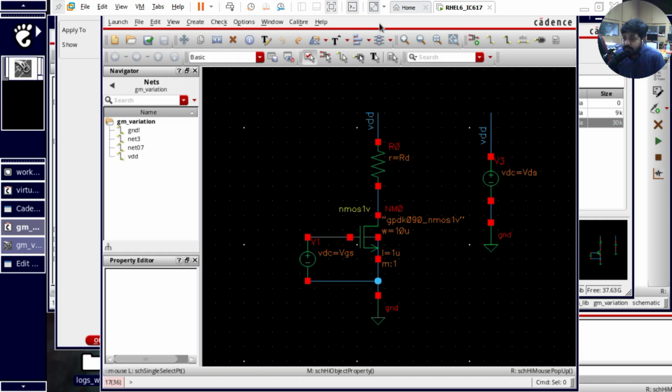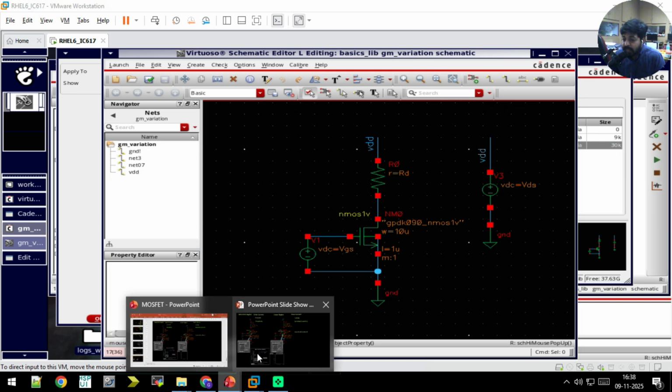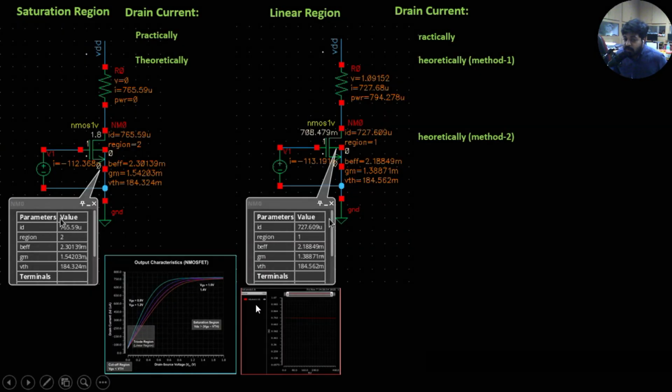And now, as I'm saying operating points, let me explain it over here, where a MOS transistor is connected with VGS. This is VGS. I'm keeping a fixed gate voltage of 1, so I'm considering VGS equal to 1. And I'm going with different operating points, where initially I'm keeping RD as 0 ohms. So I consider that there will be a VDD of 1.8 volts.